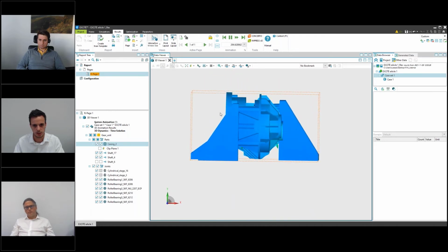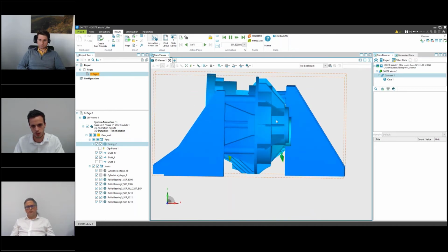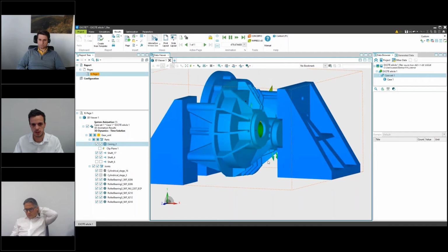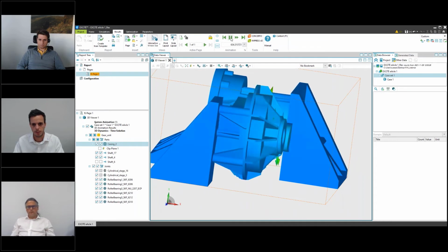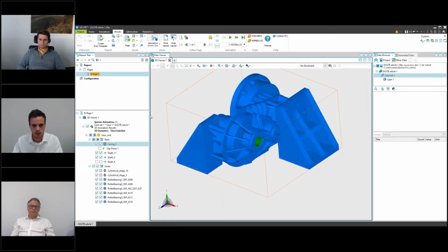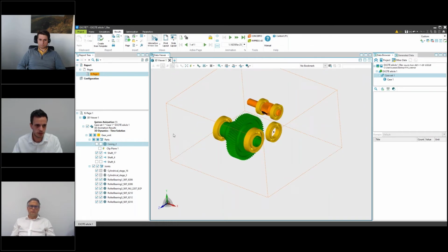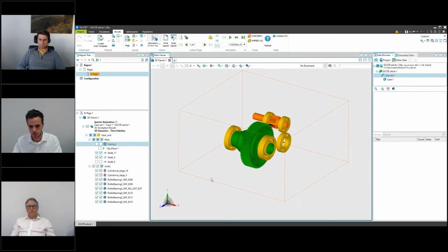And you can also see that here the gearbox is really inclined, which will automatically then tilt the shaft inside, which has a significant impact on the force distribution of this gear stage in between. Let me shortly explain the reason for this impact. The reason for the impact in this model is simply that we start a simulation from 0.